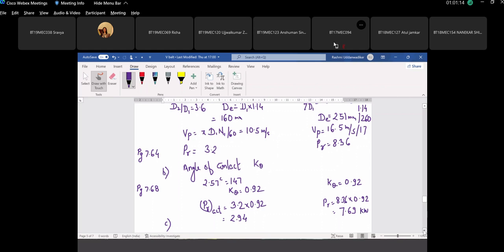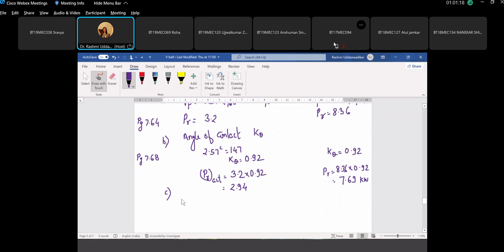Next is the length of the belt correction factor. The simpler one is the service factor, so let's take this first. Everything has to be multiplied and divided, so the sequence doesn't matter. Look at the correction factor: a motor which is driving a reciprocating compressor working for 12 hours per day. Type of driving unit is motor, running at 1440 RPM, and the driven unit is a reciprocating compressor, which will lie in the heavy duty. A piston compressor is the same as a reciprocating compressor. What is the value of the service condition?